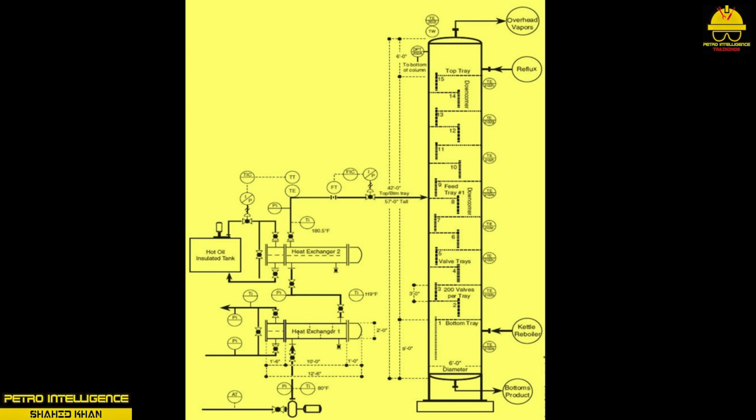To better understand how the principle of material balance works, let's consider the flow of raw materials through a column. Flow enters the column at 550 gallons per hour. This is roughly equal to 10 barrels per hour. Flow leaves the tower through one of three paths: bottom, side stream, or top. The bottom's product contains heavier molecules than the side stream or top. To obtain the material balance, add the sums of the three outlet flows. This number should equal the sum of the inlet flow.